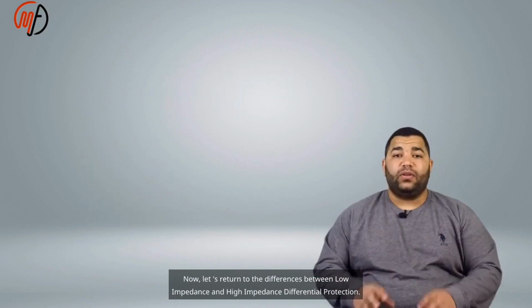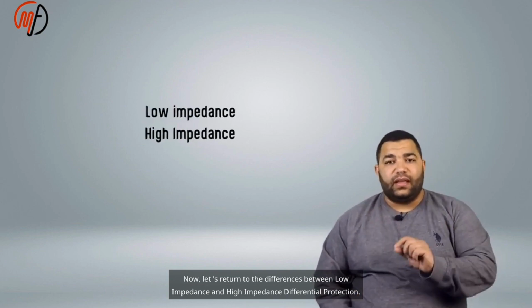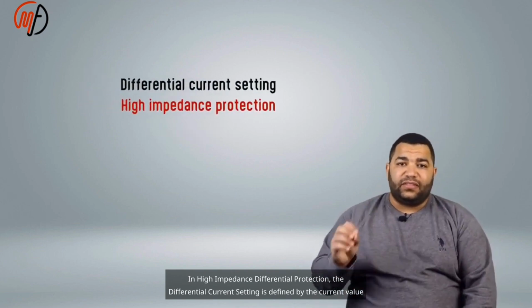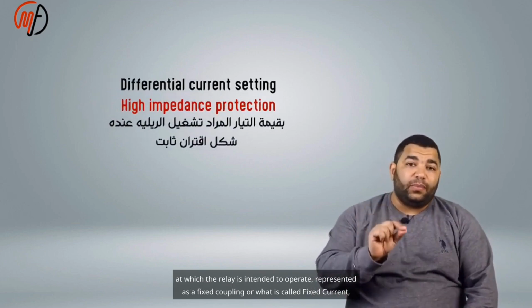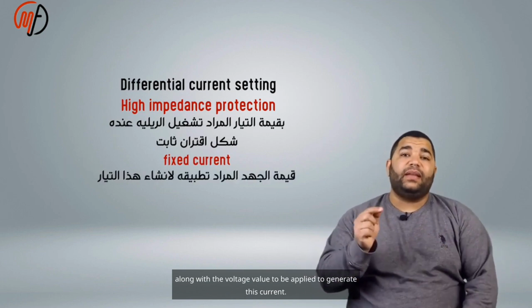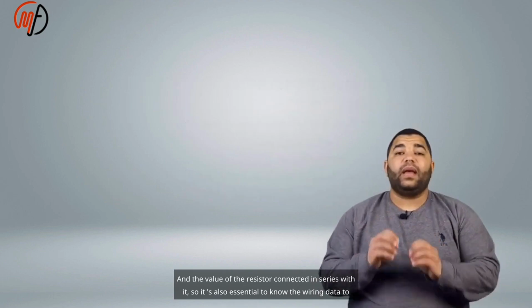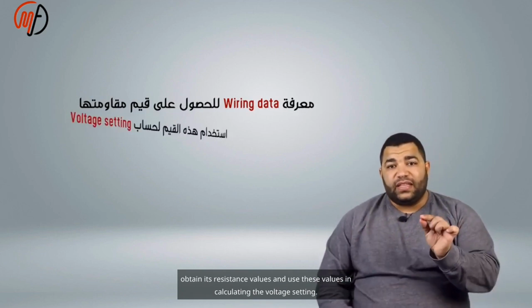Now, let's return to the differences between low impedance and high impedance differential protection. In high impedance differential protection, the differential current setting is defined by the current value at which the relay is intended to operate, represented as a fixed coupling, or what is called fixed current, along with the voltage value to be applied to generate this current, and the value of the resistor connected in series with it. So it's also essential to know the wiring data to obtain its resistance values